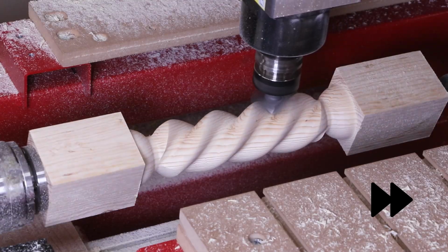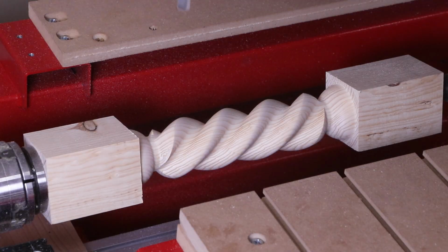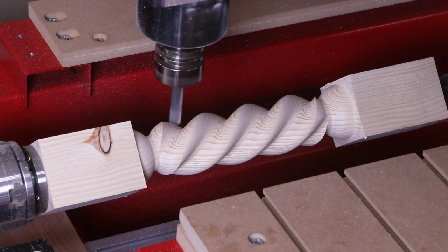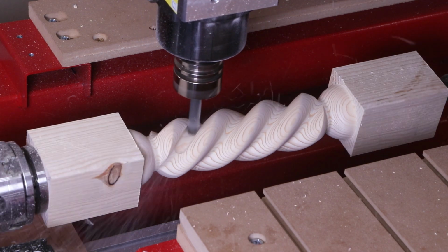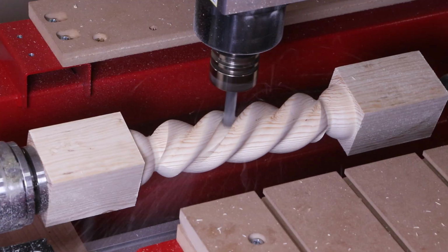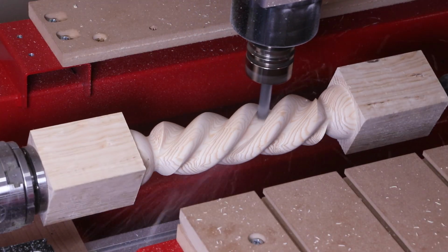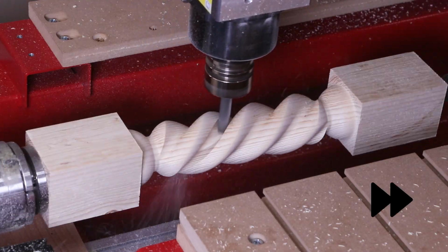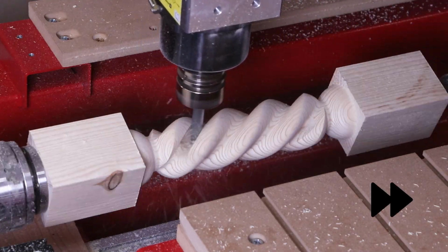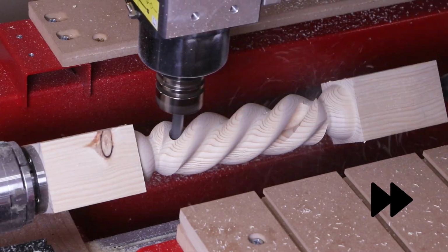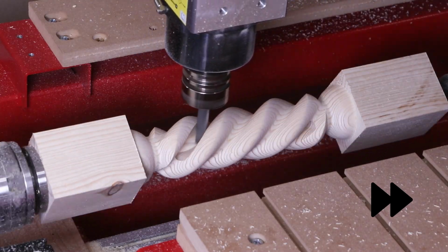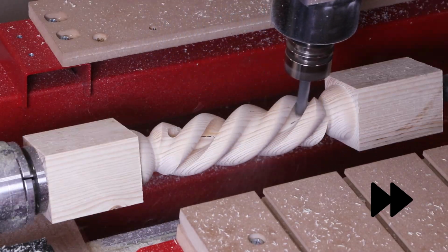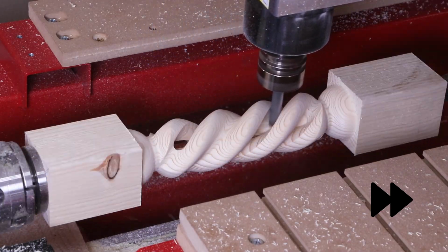The 1/2 inch cutter goes to the starting position, in this case at the 6 inch mark along the x-axis. Notice that the stock rotates to position this 1/2 inch cutter right in the center of that barley twist cut to make sure that this hollowing section is happening along the exact same toolpath for both cutters. This gradually works its way down to the center of the material for each start, and in the end, after it's pierced all three, we have a true hollow spiral effect.